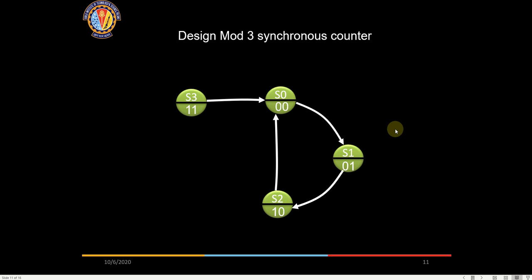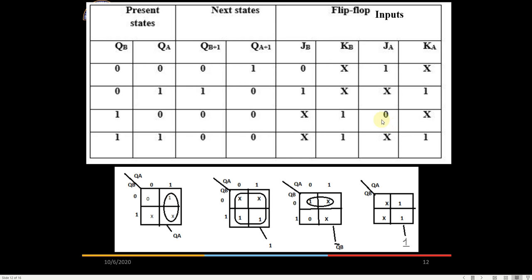This is just a state table which we have got now. Now we are going to use a JK flip-flop. Initially the condition is 0 0. Now I want 0 1. So J is equal to 0, K is equal to X, J equal to 1. This is X, 0 1. This is the next state. It is similar to last time, 1X and X1. Again, then I have put 1 0 here. And for 1 1 I am getting 0 0.